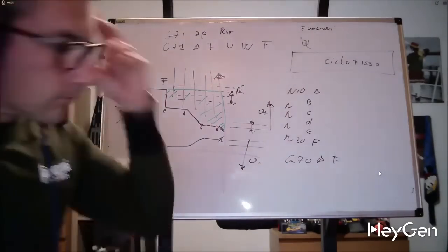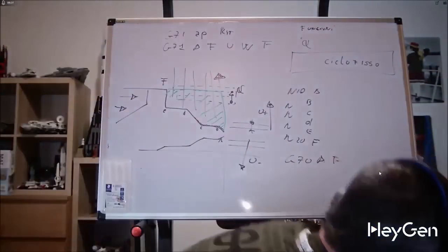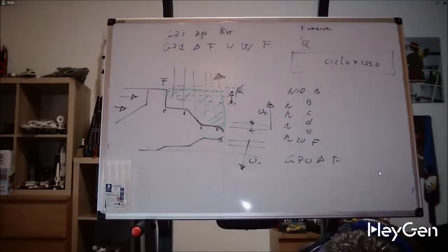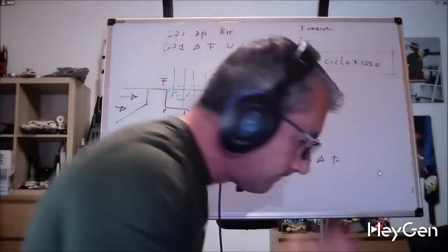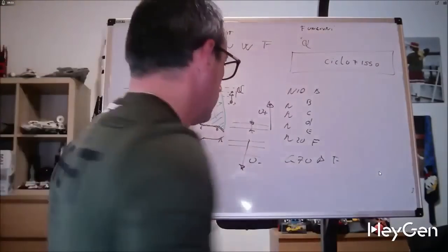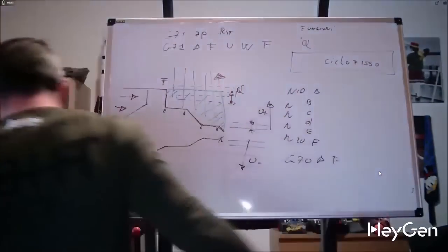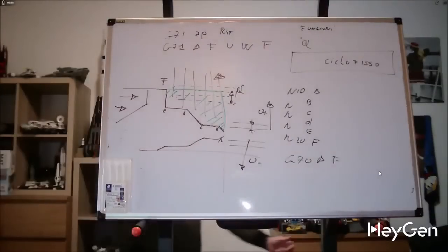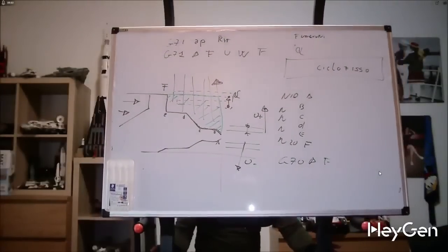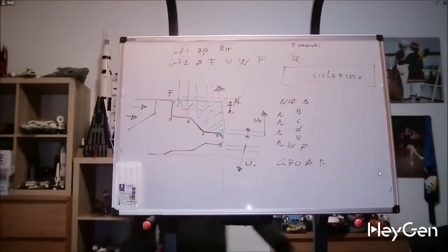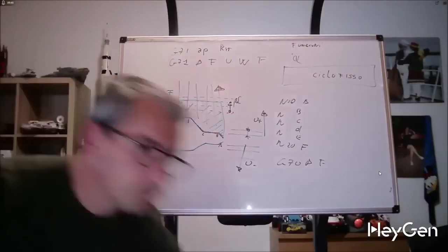exercise for you. As you can see here, we have a whole profile to hollow out, and a raw piece with a diameter of 130 and a length of 75 millimeters and a hole of 30. So what we're going to do now is work on the simulator, which you can see is a rough, I would say, nice copy of a Fanuc 31i CNC.